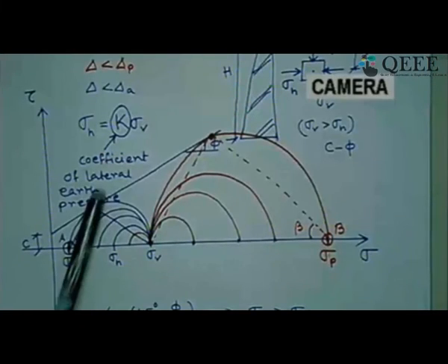The slip lines, the failure planes, I have already described that through Mohr circle, how for this Rankine case of pressure, how we are getting the inclination of the failure plane both in case of active state of earth pressure as well as for passive state of earth pressure. If we go back to those pages, I will probably try to explain it further. Yes. So you can see from here, which we have already discussed in detail, this is the inclination of the